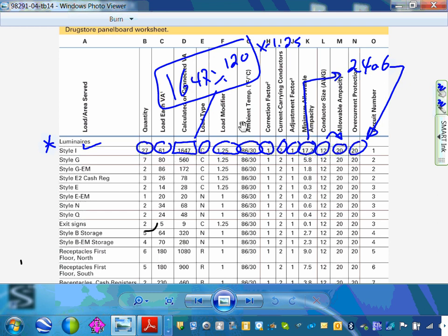Okay, that's it. Now, because it has a star, now you're gonna go say, okay, number 12. Can number 12 have a 20 amp circuit breaker? Yes. Using copper, absolutely. Yes, that's where that star comes handy. You and your stars. You got it. Yep.